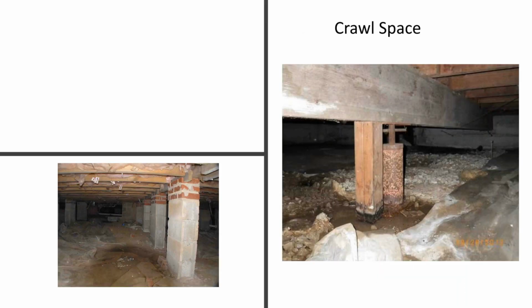Crawl spaces, this is a real issue here. They put wood against dirt, so it started to rot and deteriorate. Then they put a metal post in water, and it started to rust and deteriorate. So all of this is bad.